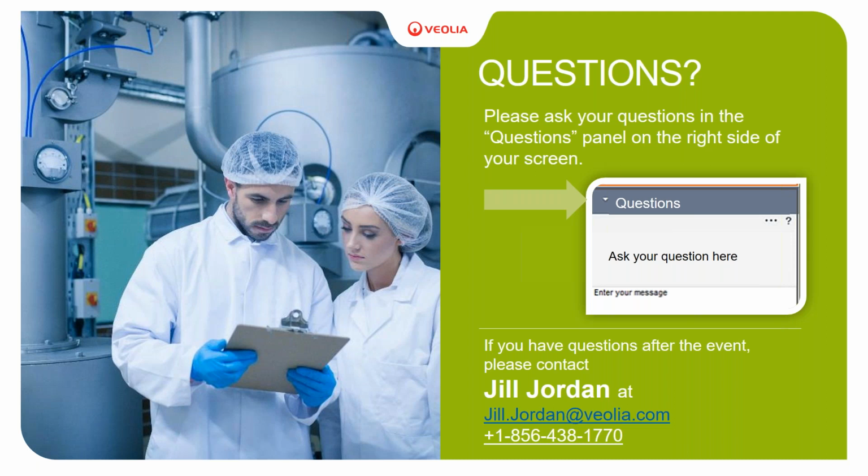And I guess the question would be, outside of just seeding, is there anything in terms of operating that reactor that would promote that transfer from flock to granular? Yes. Well, you have to have the hydraulic retention time of the influent into the digester volume be less than like 48 hours. And I don't know why that is. We just know that you don't get good granulation unless the hydraulic retention time is 48 hours or less.